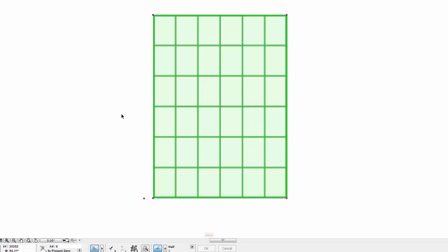Now the first stage of configuring this tool, you basically grab this node, stretch it down 100 mil, in 100mm increments, and that'll take you through the different phases. So you can see the phases here. I'll just run through them quickly and then we'll go through them in detail. So we have guide off, shape and openings, joints, boundary features, and hangers. Alright, so let's have a look at the first one, shape and openings.